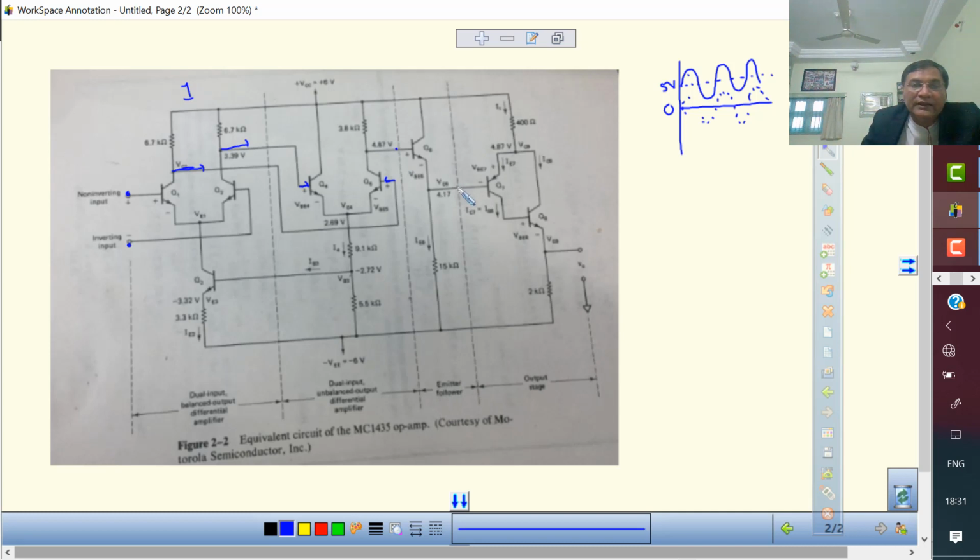And then what you are getting as the output here, you cannot use directly for your device. Suppose this is the output, it is already amplified. Suppose you connect it with the speaker. Okay, this is your speaker. You connect this point here, and one is grounded. So there is some problem. What is that? There may not be matching. This is not matched with the input of this one.